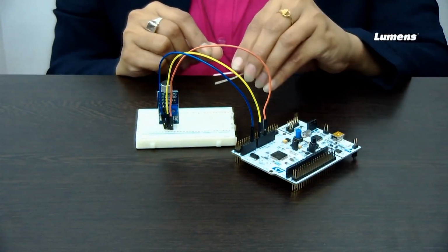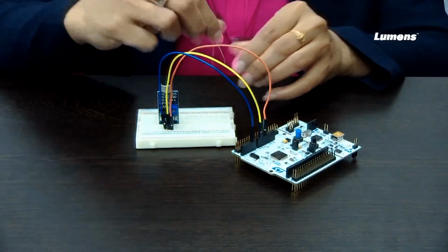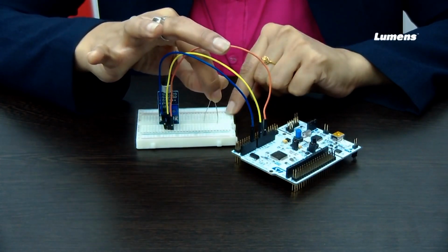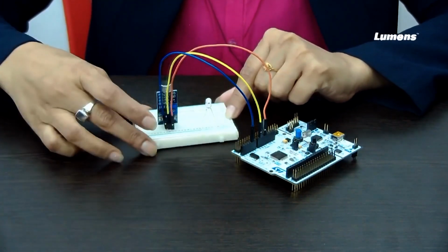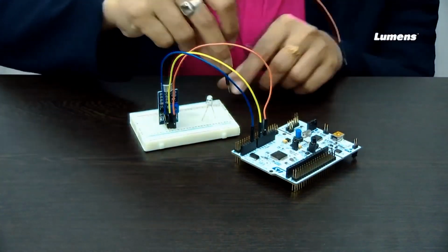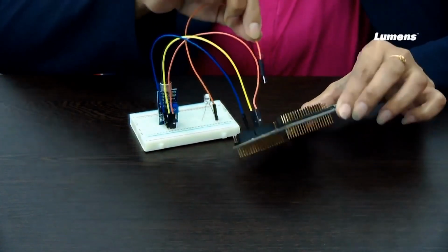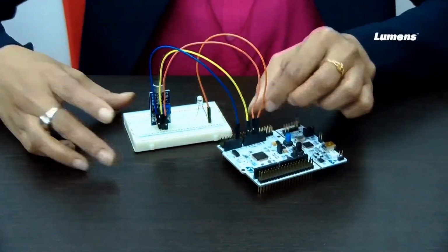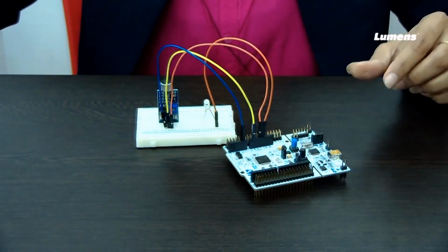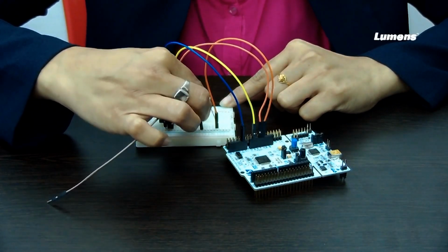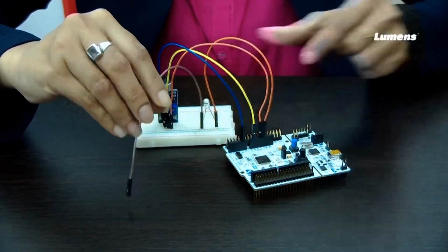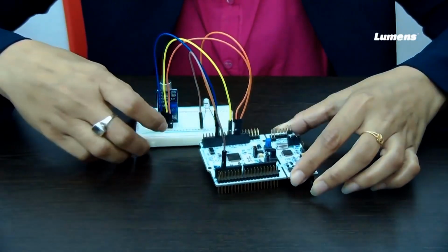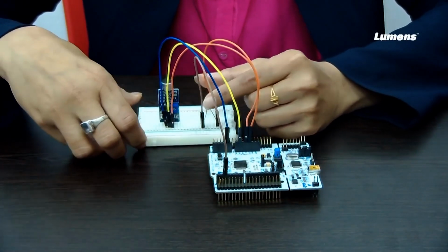So I have to connect this LED. We already know the connection of the LED, so how we are making it here is like this. This is the anode. The anode I am connecting directly to the 3.3 volt that is present in this STM board, and the cathode I am connecting to port D2. The way I have programmed, you can connect to any port you want. As I have programmed it in this fashion, this is how I make the connection.